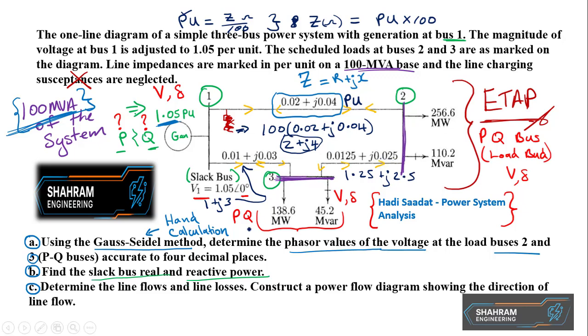Yeah, so these are the values that will be plugged into the ETAP software. Again, as I said, remember all of these values are in pu, per unit. So if we want the real value, pu is equal to the real divided by 100, and then to get back the real value, we do the pu times 100. That's where I'm getting back the real value.